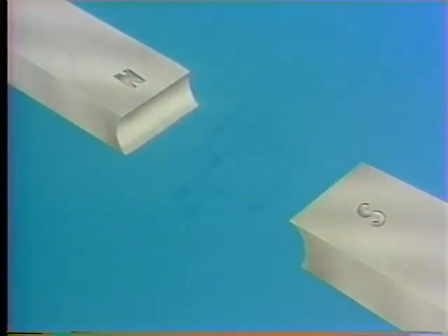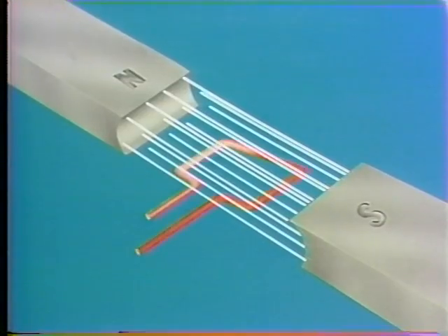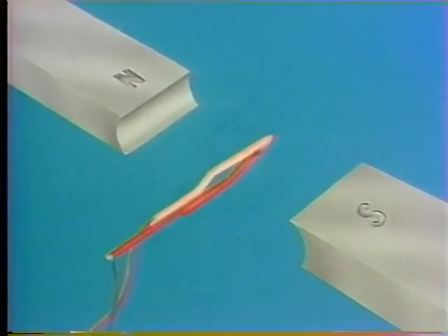These two permanent magnetic poles produce magnetic lines of flux that extend from the North Pole to the South Pole. This is the main magnetic field. Between these poles, we'll add a loop of wire to act as a conductor. Now, if we were to wire the ends of the conductor directly to a DC power supply and apply voltage, the conductor would turn, but only as far as the wires would allow. So we need a better way to make a connection between the motor and the voltage source.